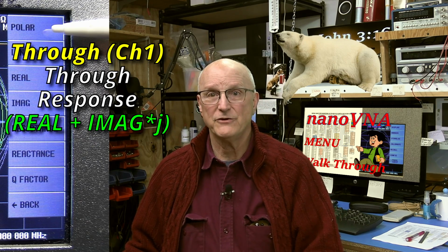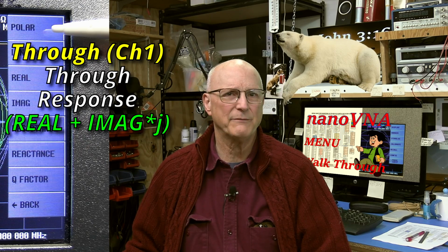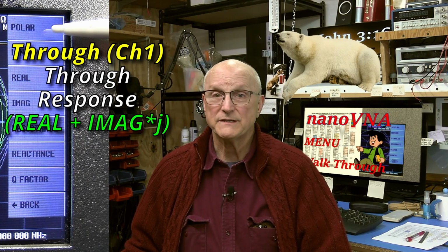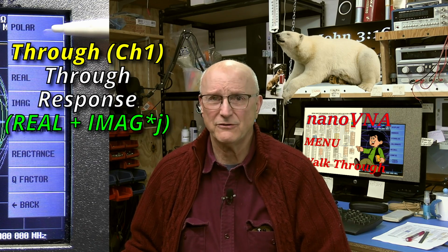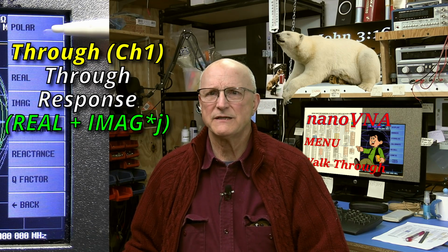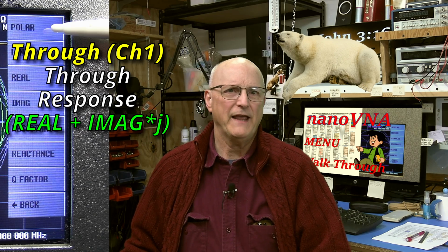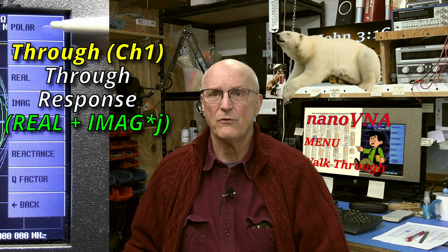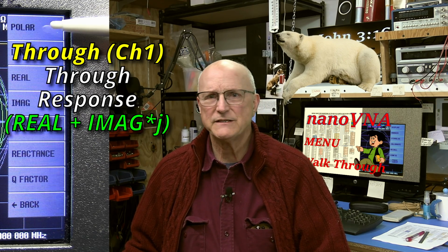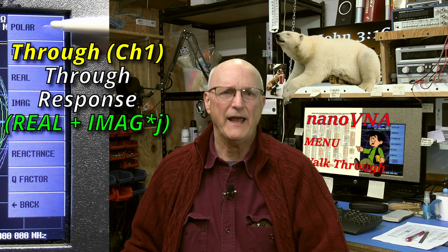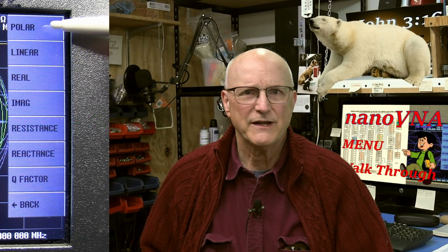What this means is that the values you see here are relative to the incident signal coming from channel 0. A value of 1 plus 0j means that we're getting the exact same signal into channel 1, or port 2, that is being sent out channel 0, or port 1. The angle that the resulting vector makes to the positive horizontal axis for any given point is the phase of the signal relative to the signal from channel 0 at the given frequency. The length of that vector is the magnitude of the signal relative to the signal from channel 0. In the case of a filter or other passive device, the magnitude will never be greater than 1. In the case of an active device like an amplifier, the magnitude may be greater than 1.